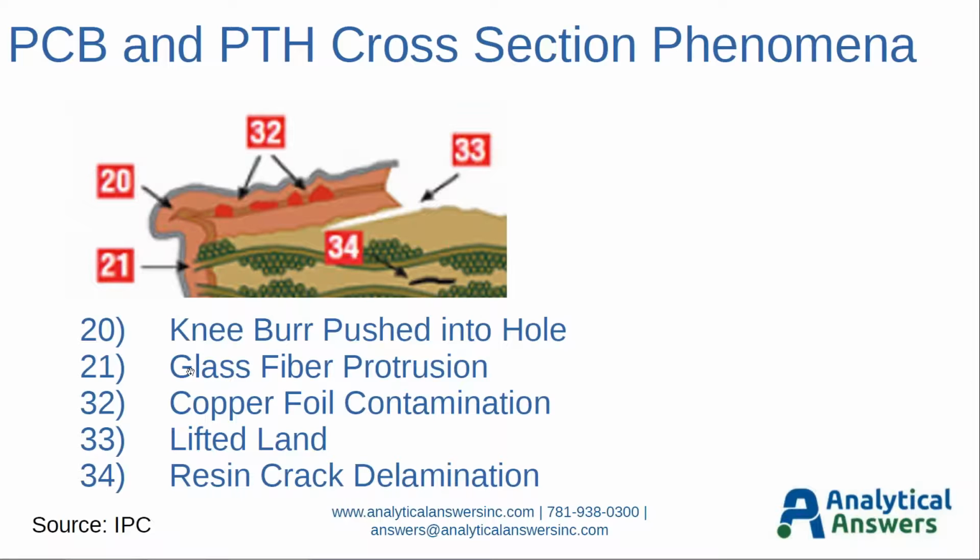The next thing we're going to talk about is number 21 here, the glass fiber protrusion, and we're going to see this as well in one of the sections that I prepared, where the glass fibers are actually punching through into the copper plating here of the hole.